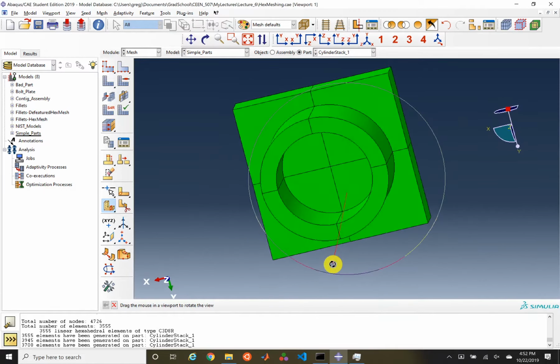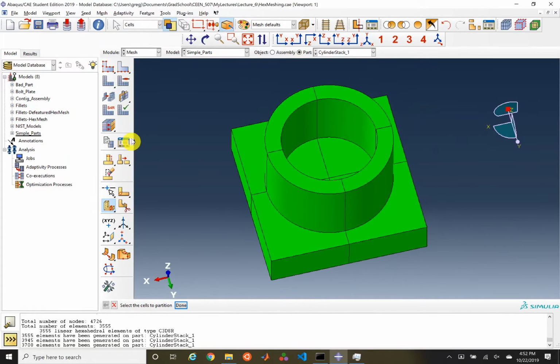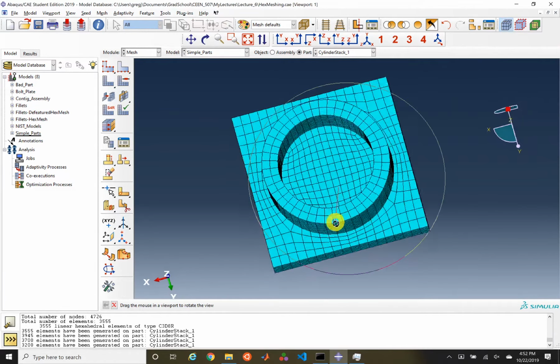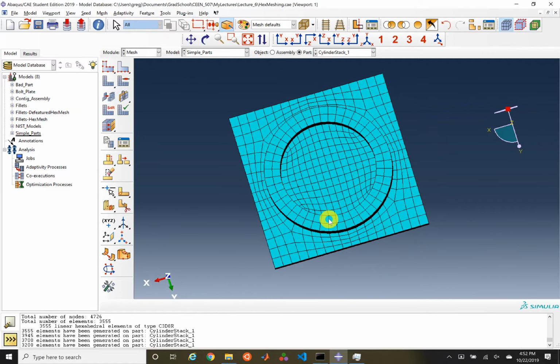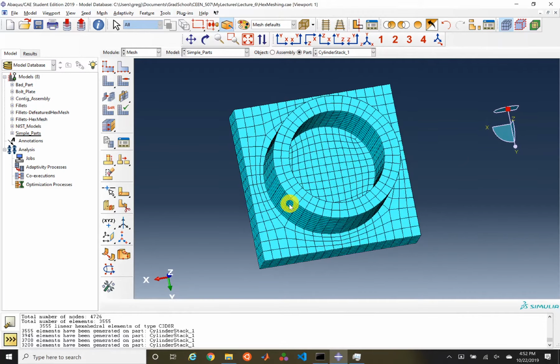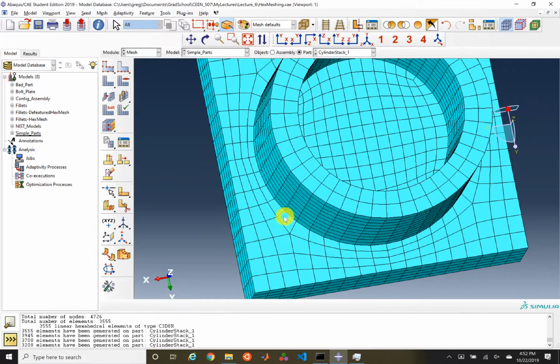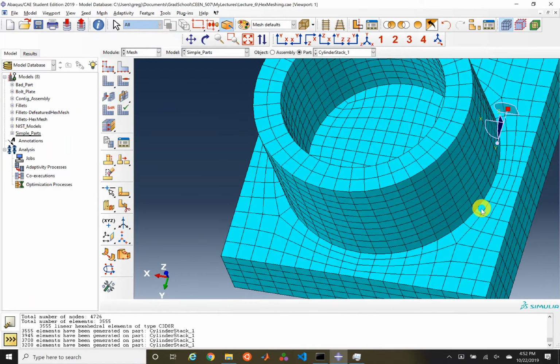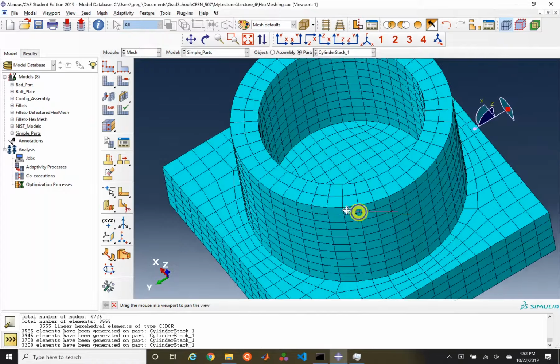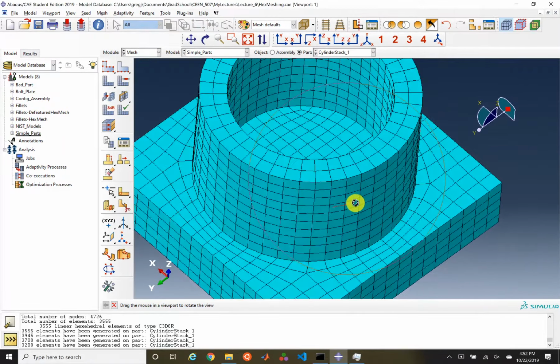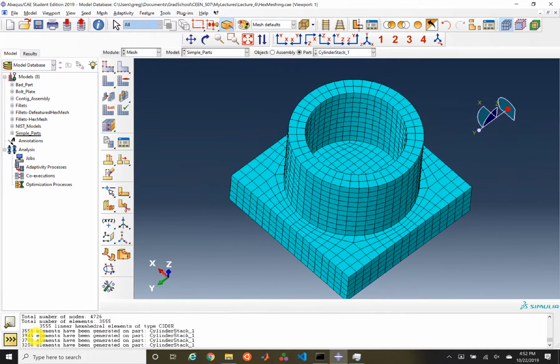Wow, and now our entire geometry has turned green. If we construct a hex mesh here and show it, we now have a mesh that looks kind of beautiful almost. We're following all of our hexahedral elements along this base, where there might be some stresses, following the overall shape of that cylinder. So yeah, this is a really good mesh. Again, we see 3,200 elements, compared to our original mesh at 3,500 elements, so we've even been able to decrease our element count a little bit.